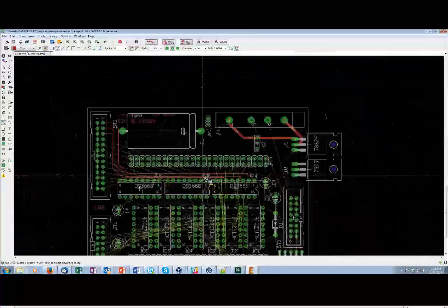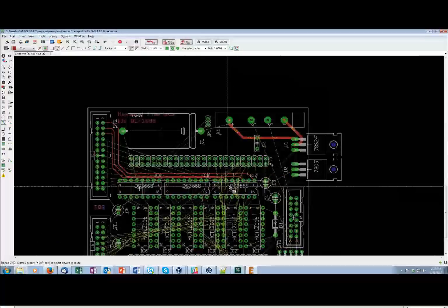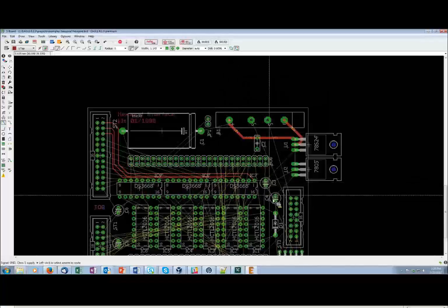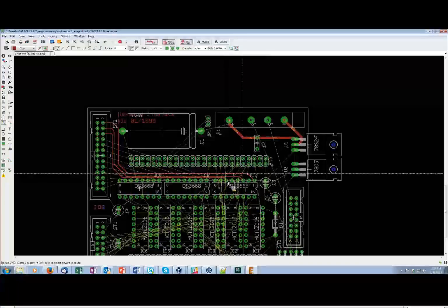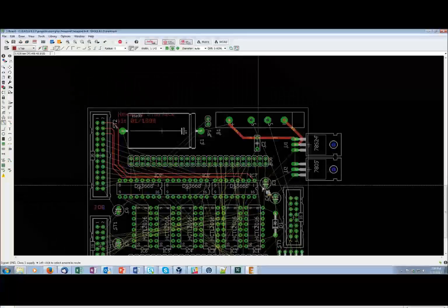Do you have a component that's going to dissipate a lot of heat? You have to take that into account to avoid maybe nearby caps having their lifespan shortened or affecting their performance. There are many components that are very sensitive to heat, so you have to keep that in mind.